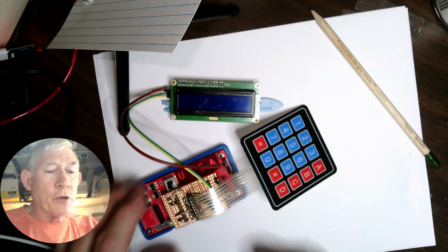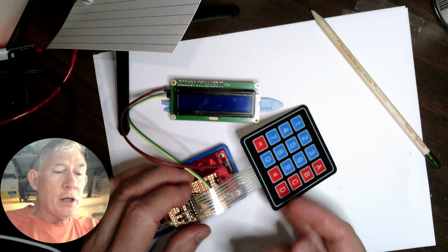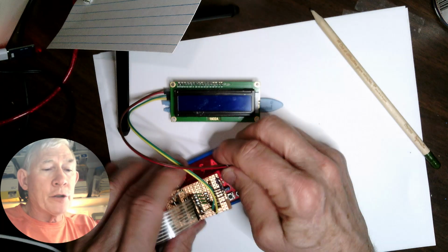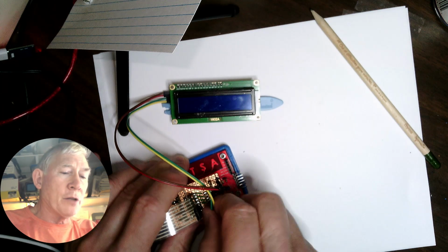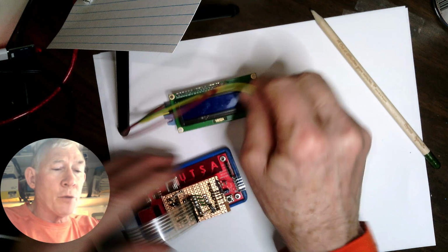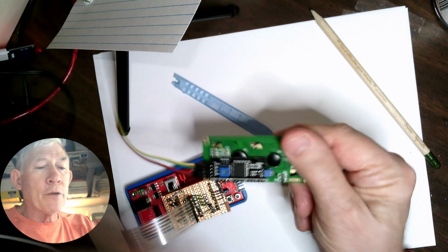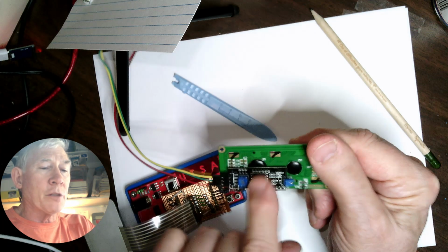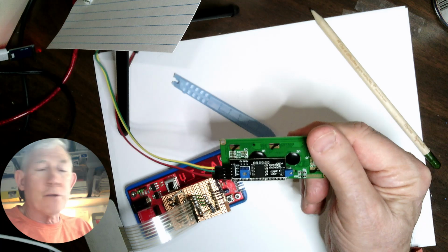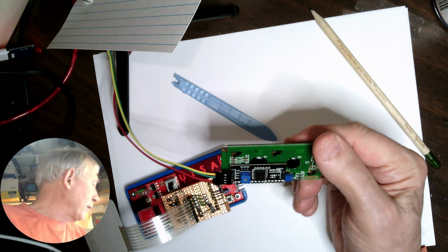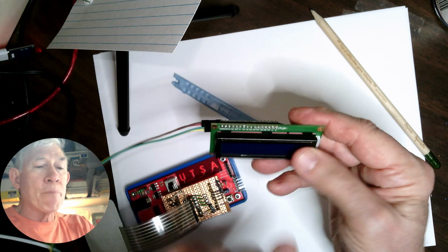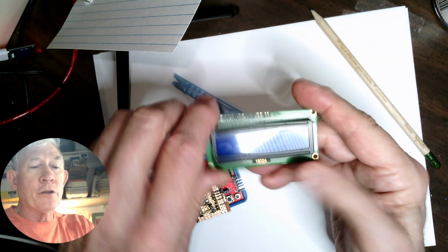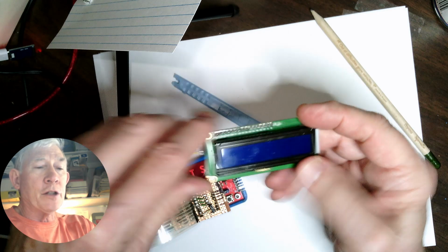And then we also use the I2C with power and ground here, and then I had to bring out the 2 I2C pins on my adapter board because my adapter board covers up. And we have a little board on the back of this that brings these pins out using this PCF 8574 or 76 or something chip, which basically connects 8 pins that control this LCD display.